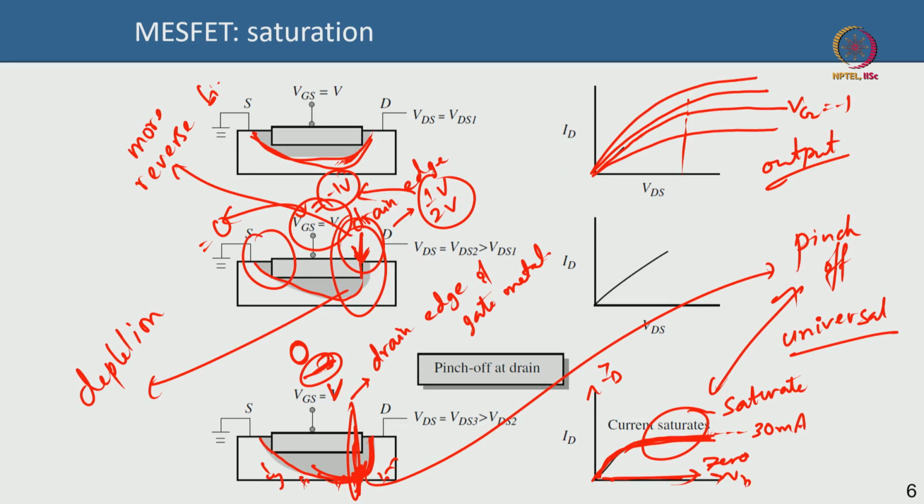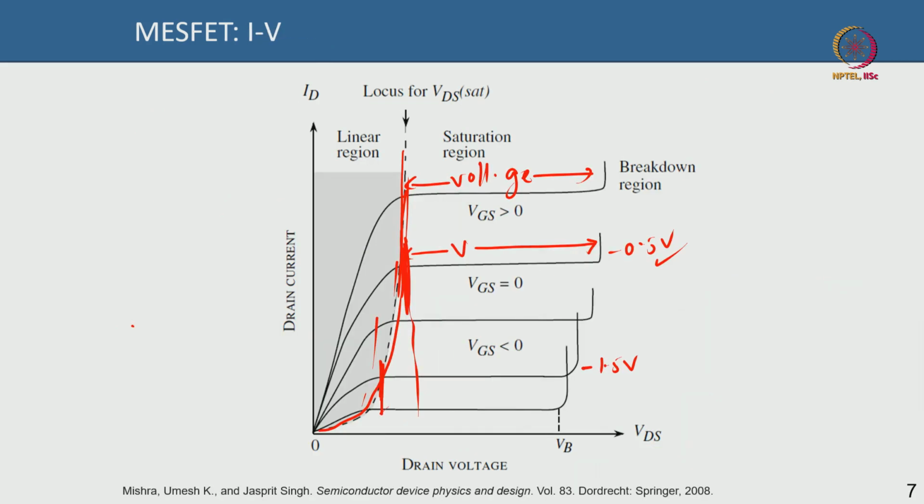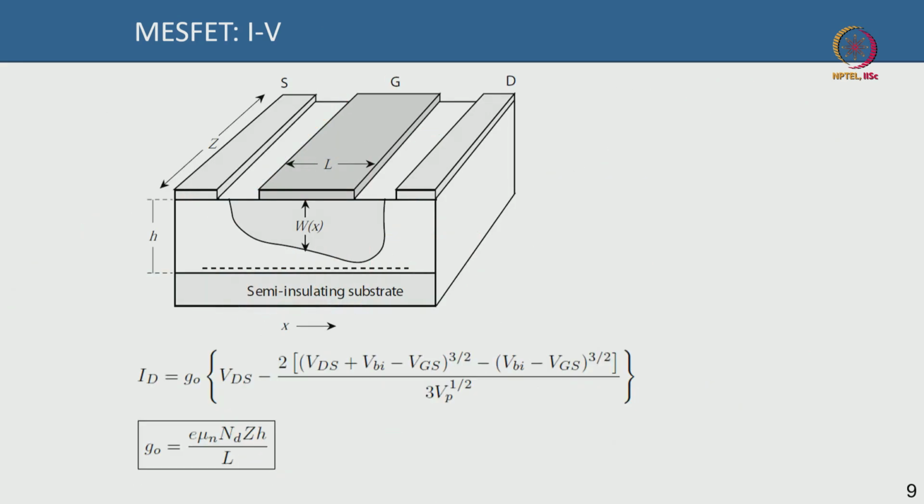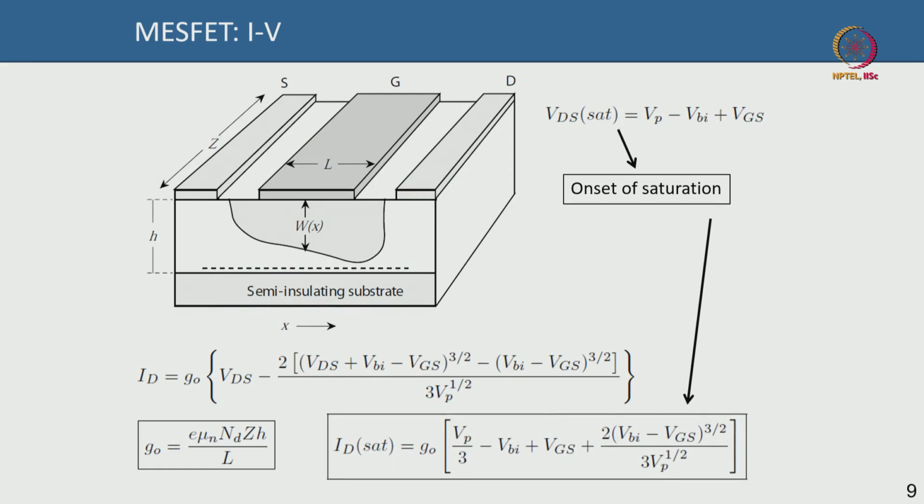Essentially what is happening is that you are accommodating the gate-drain voltage drop in calculating the pinch off, and that is why you are doing that. So, if I plug in this value of VD sat, then I get this expression of drain current, where I essentially replace this with this value.